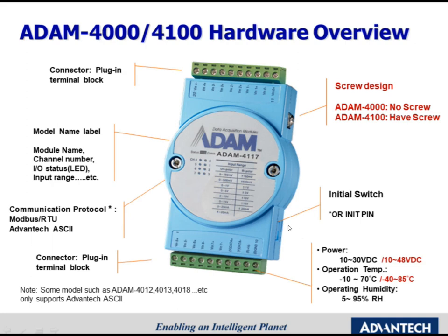There is an initial switch on the right side of the module. You might see an initial pin on the bottom channel of the module. By adjusting the initial switch or shorting the initial pin to ground, we can put the module into initial mode to change the module configuration.